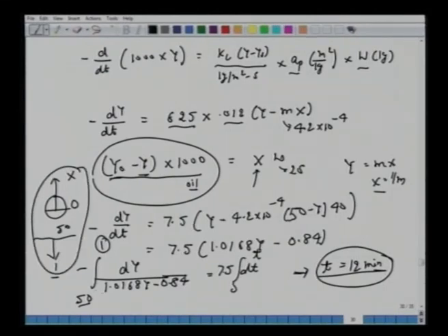All right, notice that this is the first order here. So to reduce 50 to 0 or any very small value, it will take a very long time. If we can plot it here, it is the first order starting from Y0 to a very small quantity here. So this example we have chosen on batch adsorptions. We of course qualified by saying that all resistances are negligible, and it's only interphase resistance which is predominant. So diffusion resistance in interphase mass transfer is significantly higher.